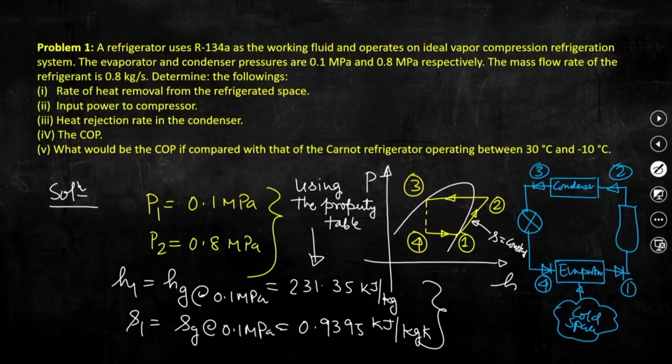Now, if we go to the next slide, then what is basically T sat? So, basically I am writing here that T saturation at 0.1 megapascal is minus 26.43 degree Celsius. So, basically this is the saturation temperature corresponding to that pressure for this particular refrigerant.